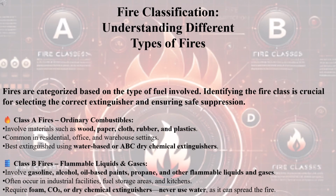Fires are categorized based on the type of fuel involved. Identifying the fire class is crucial for selecting the correct extinguisher and ensuring safe suppression. Class A fires, ordinary combustibles, involve materials such as wood, paper, cloth, rubber, and plastics. Common in residential, office, and warehouse settings. Best extinguished using water-based or ABC dry chemical extinguishers.